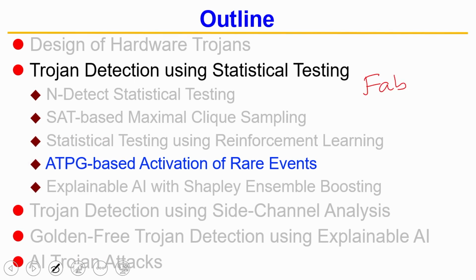the chip comes from the fab, and remember there are millions of them coming. For a processor it could be thousands to millions, for memory it could be millions to billions of copies, and there is something called automatic test equipment. You put each chip on the board, run those tests, and then either it passes or it says there are a few lines which are defective.